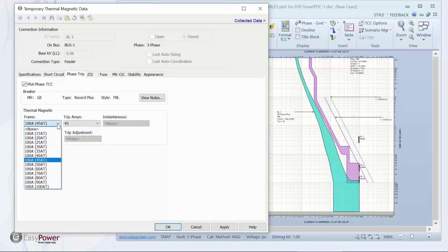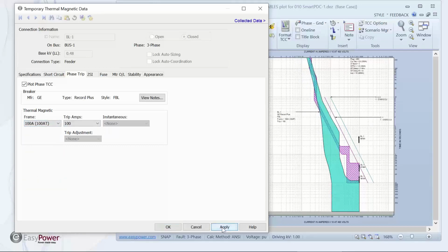If we have a different sized breaker, we can see that, and the width of this column is set by the manufacturer. And again, as long as we are using this in the proper application, the right-hand top of this plot will indicate where the breaker is guaranteed to clear.